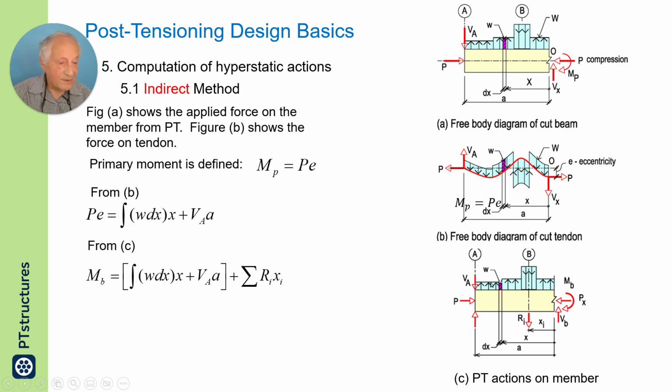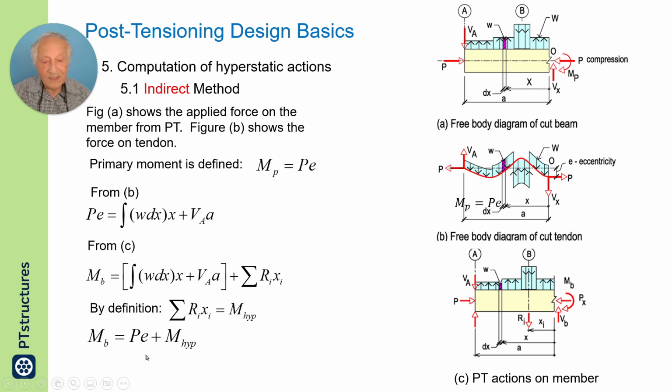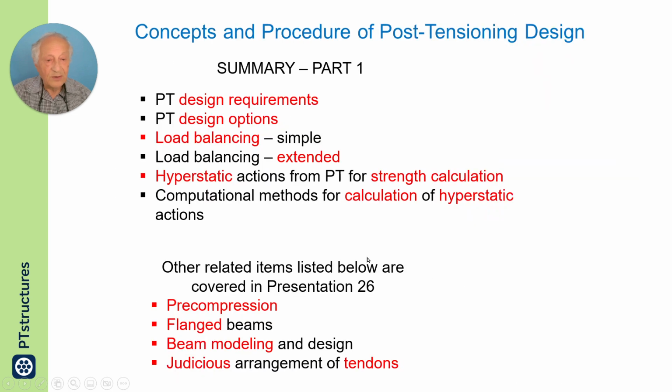I will get this expression, compare these together, and by definition, this is the hyperstatic moment. Reactions times distance are the hyperstatic moment, and this can simplify to the hyperstatic moment being the balanced moment minus PE. This has been in common use by many of our fellow engineers, and they still use it, and it applies well to the configuration that I showed you here for prismatic members.